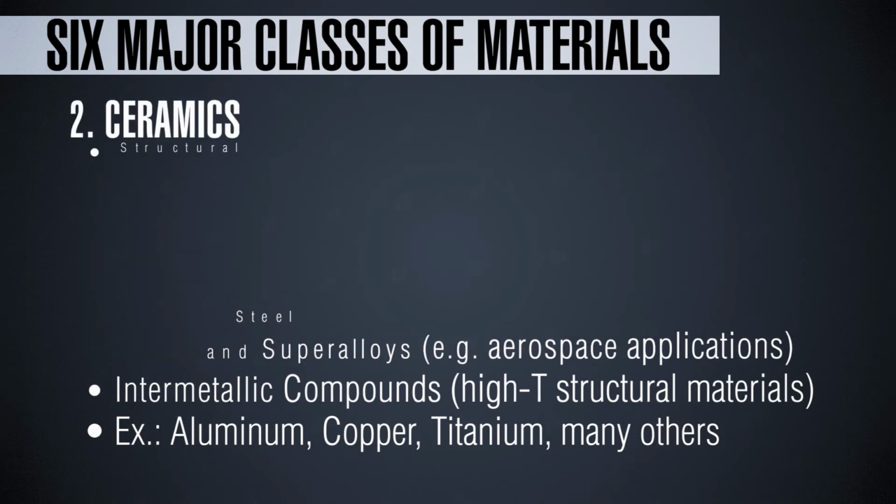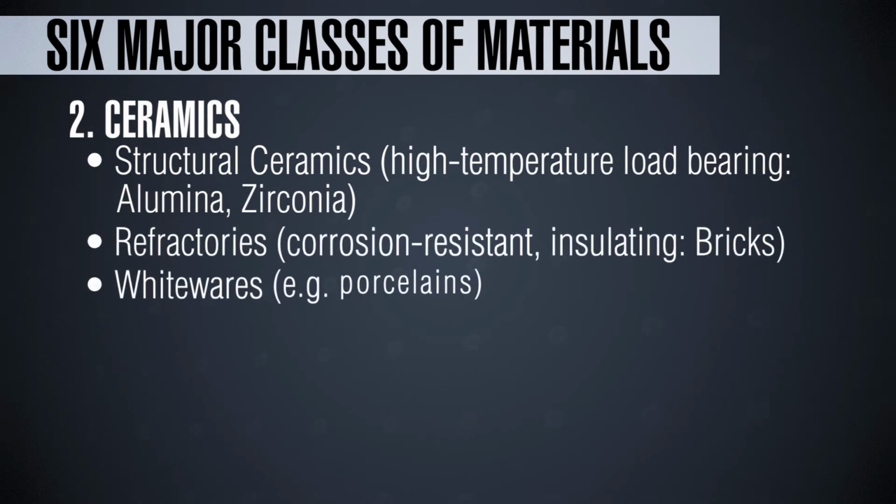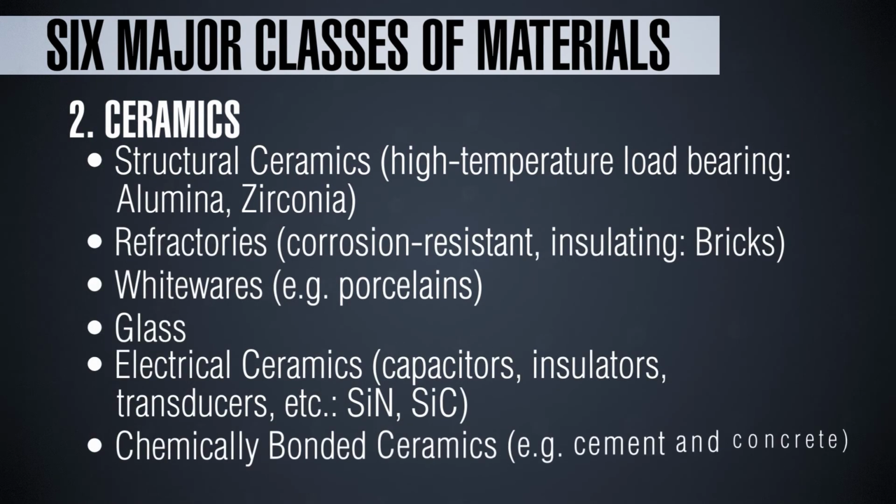The second major class of materials is that of ceramics, and within that class we may differentiate and also include the glasses. Ceramics are usually metal oxides, and they are usually characterized by extremely high melting temperatures, much higher than the corresponding metals. Of course, there are exceptions to this, and not only metal oxides but also mixed compositions are used, in particular for engineering applications.